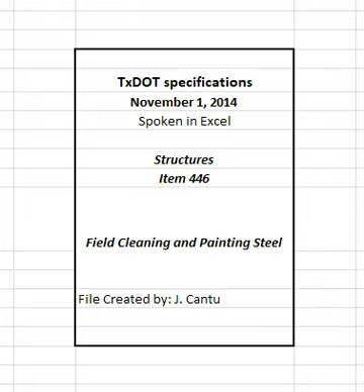4.7.4.5.7 Special Protection System. Apply paint as shown on the plans. 4.7.4.6 Temperature. Do not apply number 810 prime coat when the steel or air temperature is below 50 degrees Fahrenheit, or when the steel or air temperature is expected to drop below 50 degrees Fahrenheit within 2 hours after application. Follow product data sheets for temperature requirements for all other paints.